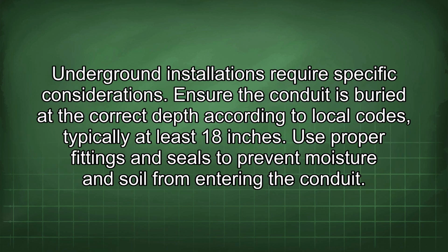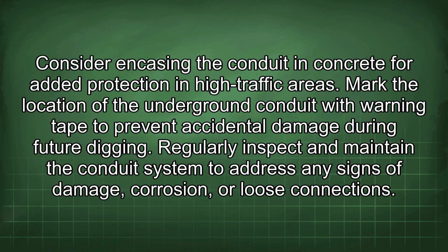Underground installations require specific considerations. Ensure the conduit is buried at the correct depth according to local codes, typically at least 18 inches. Use proper fittings and seals to prevent moisture and soil from entering the conduit. Consider encasing the conduit in concrete for added protection in high-traffic areas. Mark the location of the underground conduit with warning tape to prevent accidental damage during future digging.